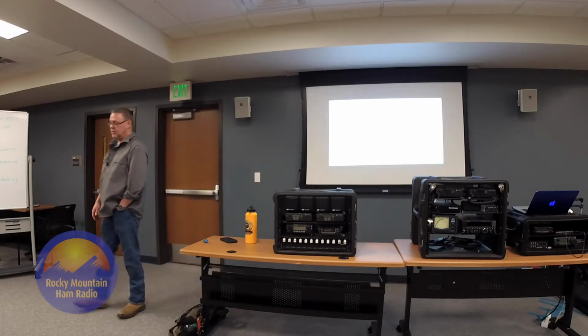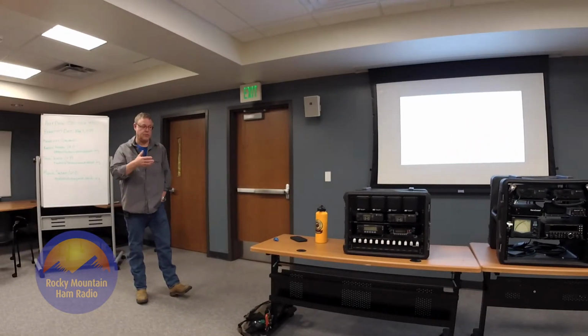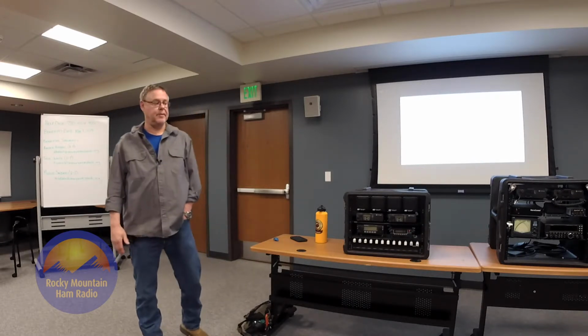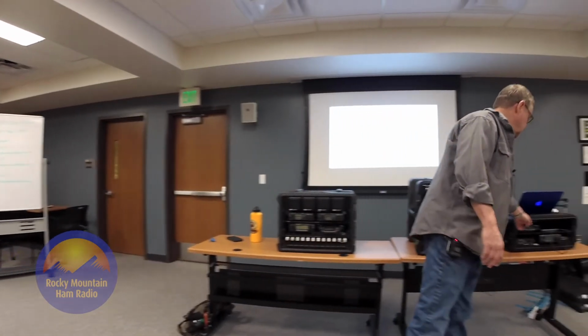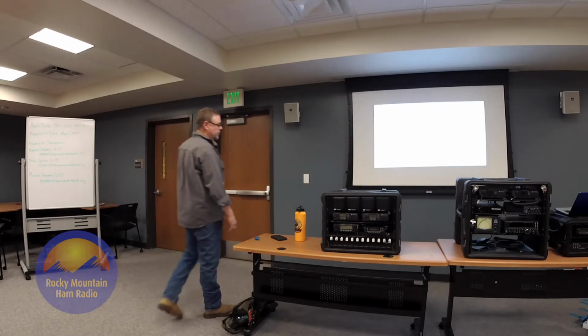Keep in mind the thickness. If you're running 100 watts, 12 gauge will do it for a typical 100-watt radio. 10 gauge is better. Step up a little bit and run a little bit bigger wire if you're going to run 100 watts to an HF transceiver. Everything else you can get by with usually 12 gauge, or most of these, like one of these radios here, you can go down to 14 gauge, but keep in mind, research your wire sizes and what their current capability is.